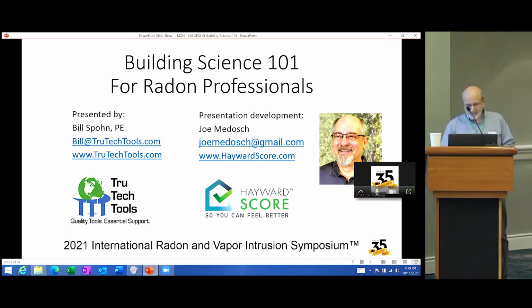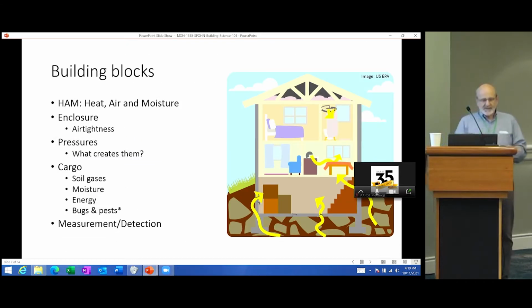So I'm going to go through this presentation and talk about Building Science 101. Some of the building blocks of building science are realizing what we're trying to detect and analyze is heat, air, and moisture. Easiest way to remember it is HAM. The movement of heat, air, and moisture really lends towards the performance of the building, the energy, the indoor air quality, and the overall health of the building, durability.